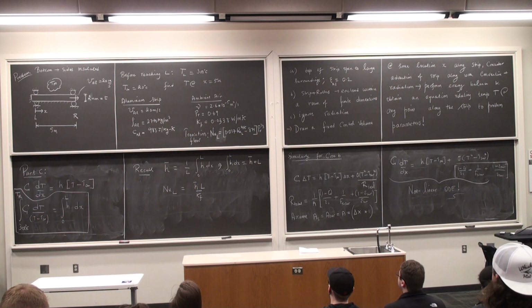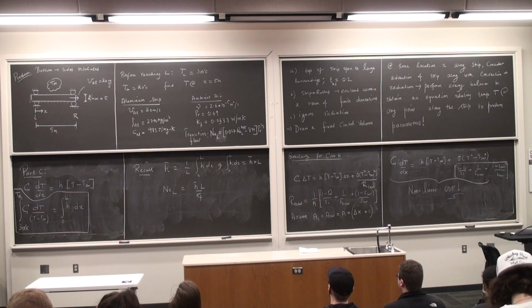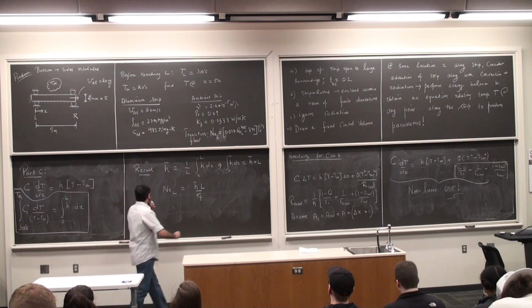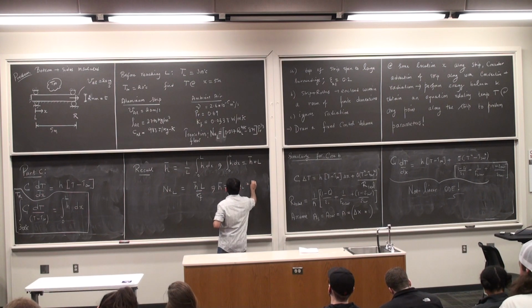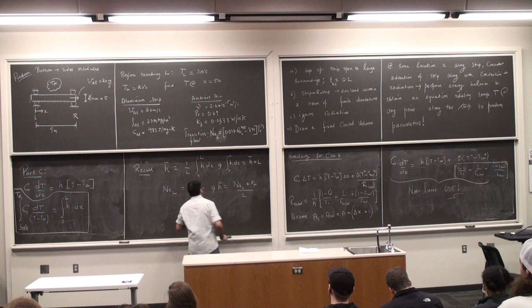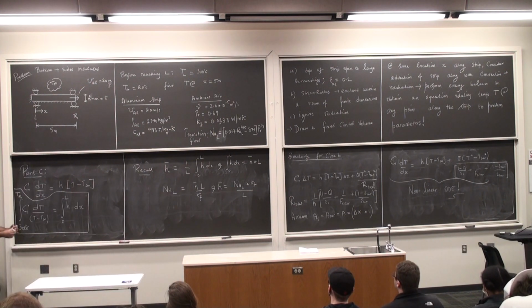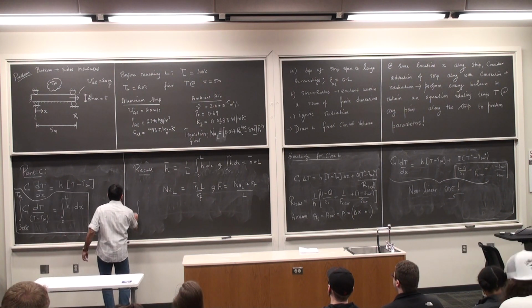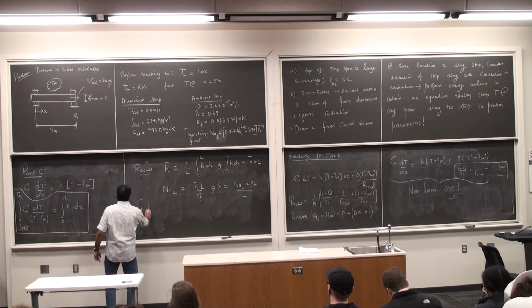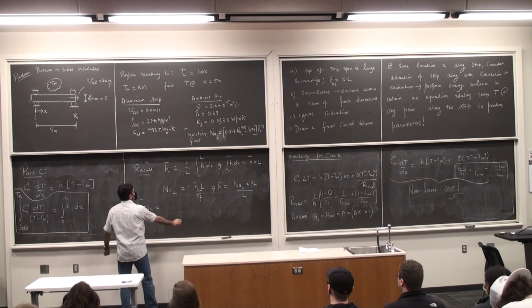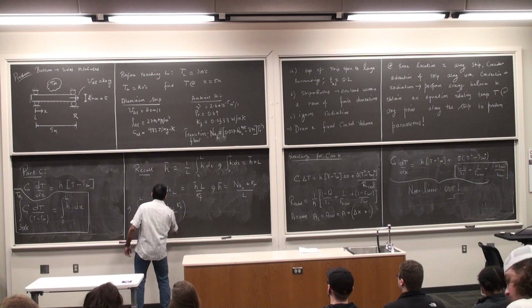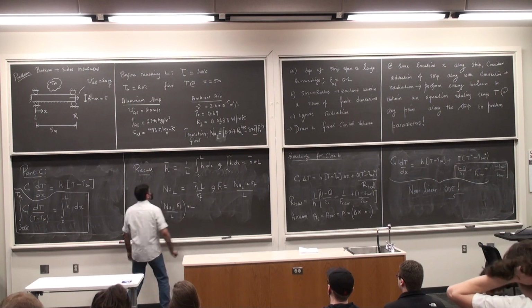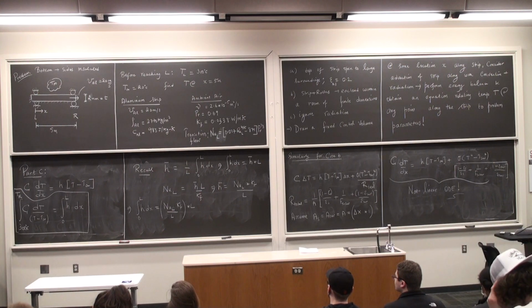You see why we are bringing the bulk Nusselt number is because that's what we've been given. Look at the top panel there, transition flow. And from here I see that h bar is NuL Kf by L. So which means this integral is actually something that is a piece of cake. You don't even need to do the integration. So integral 0 to L h dx is just h bar, which is NuL Kf by L multiplied by L. The L and the L cancel off.